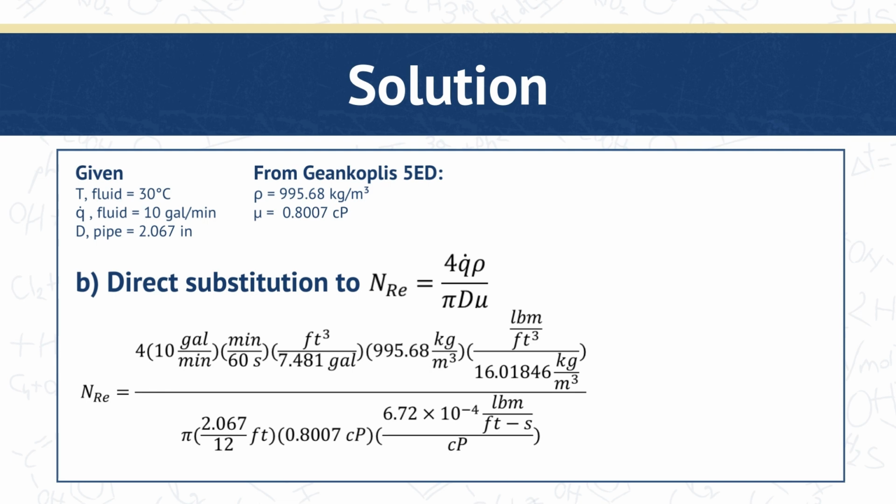So this large expression on your screen is simply a complete substitution of our given values. Take note that your units must cancel out. Generally, for English units, I advise converting all mass values into pound mass, lengths to feet, time to seconds, and such.